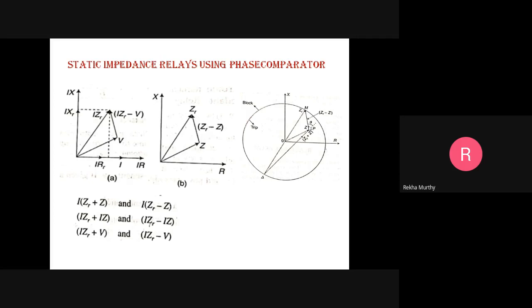Now the next case: how to realize this impedance relay using a microprocessor. In a microprocessor-based relay, we compare two parameters, that is IRMS and VRMS. There are a number of techniques that can be used for this computation. One technique is to use IDC and VDC, as they are proportional to IRMS and VRMS. VAC and IAC are rectified by a rectifier circuit to obtain VDC and IDC. These rectifiers make use of ICs and diodes.